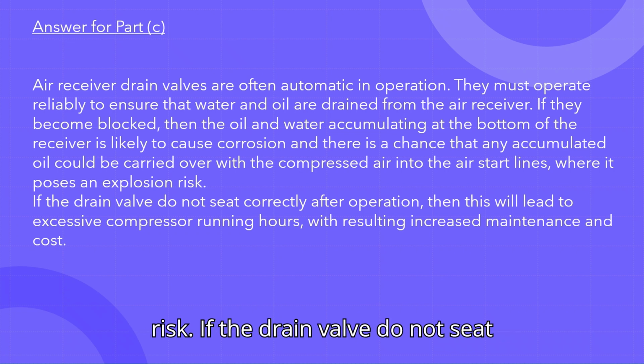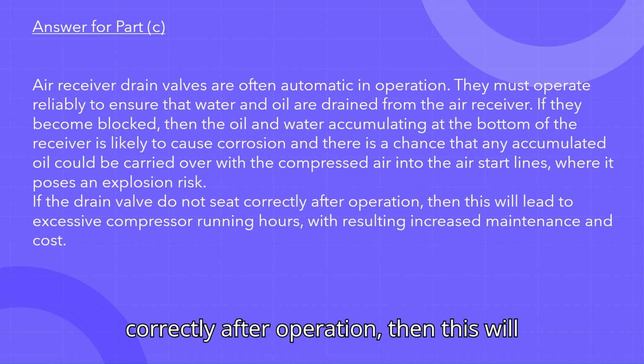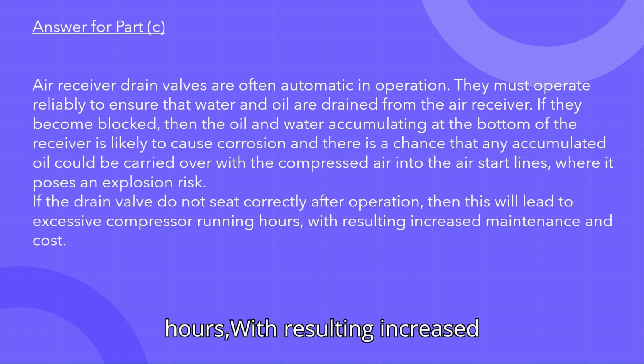If the drain valves do not seat correctly after operation, then this will lead to excessive compressor running hours, with resulting increased maintenance and cost.